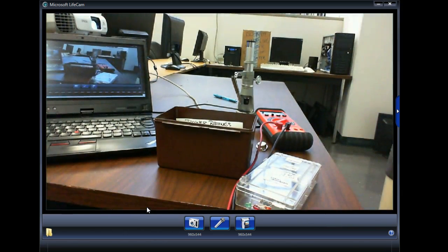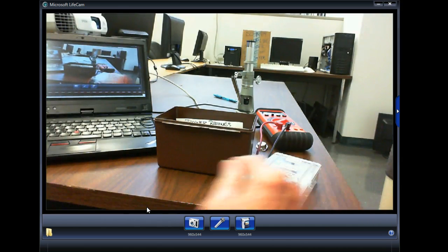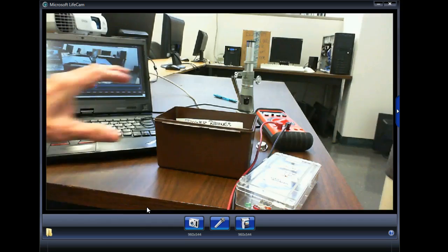So you just learned how to check a diode. It checks the diode real fast. When you put your black lead on the cathode and the red on the anode, for this type it'll measure around 6/10 to 7/10 of a volt. If it measures 0, you throw the diode away. If it measures overload in both directions, you throw the diode away. Very easy to check.